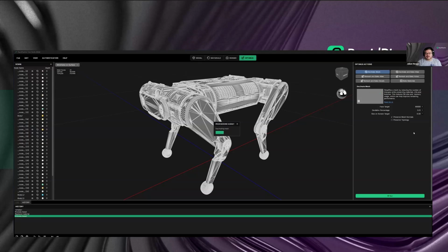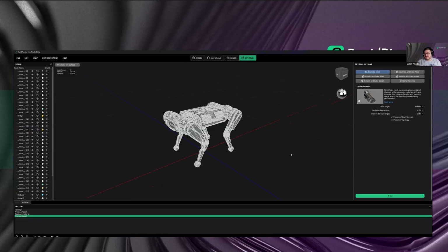Actually, we also have a built-in safeguard basically. So if a mesh would completely break, it will actually tell you in the command log that it tries to rerun it with a slightly higher target than you set. But this usually appears only in very rare cases. And I think in this case, because I already assigned UVs, the recommended workflow is to first do a decimation if you really know where to go and you need to go downstream, for example, and then create the UVs, assign the materials and so on. But yeah, usually should work both ways.